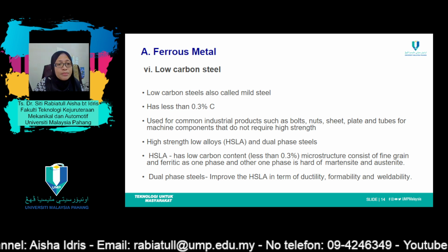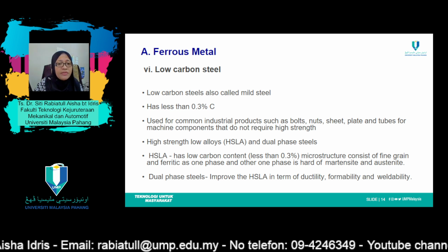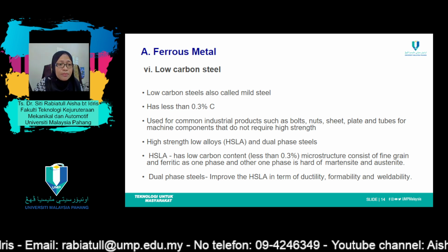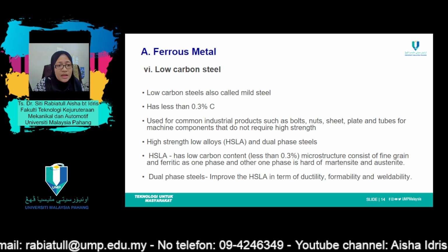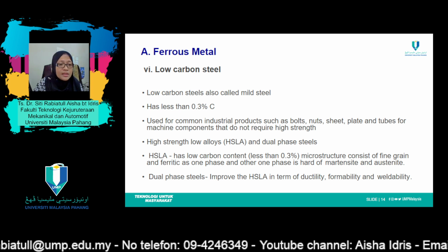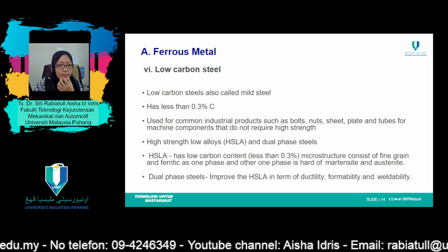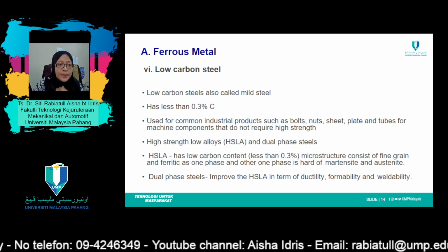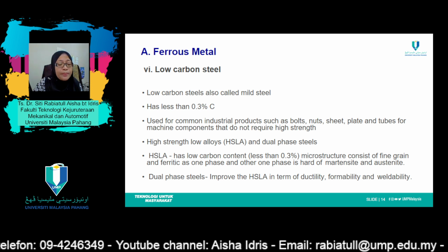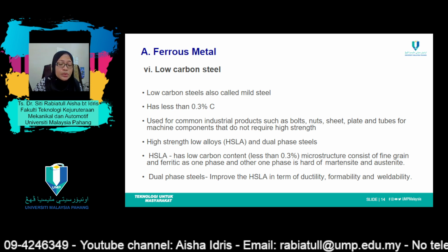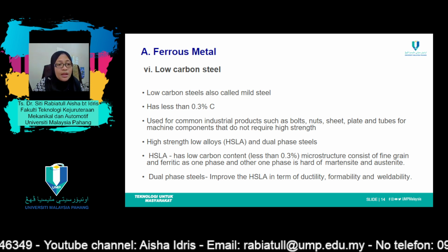Most may be strengthened by heat treatment, giving tensile strengths in excess of 450 MPa. The HSLA steels are more resistant to corrosion than the plain carbon steels, which they have replaced in many applications where structural strength is critical.